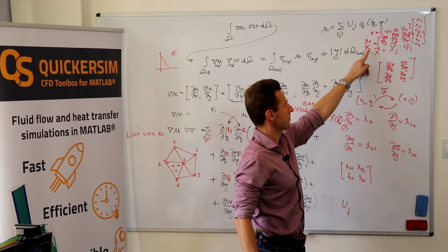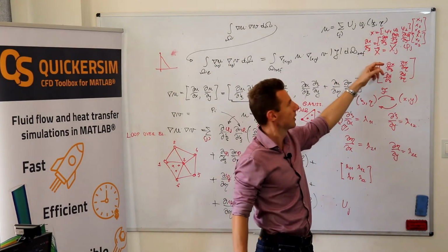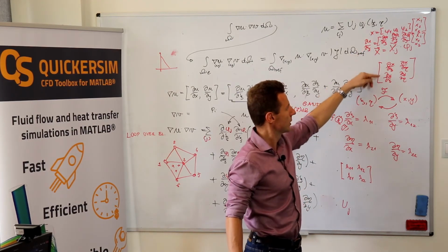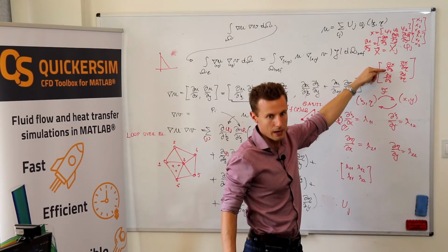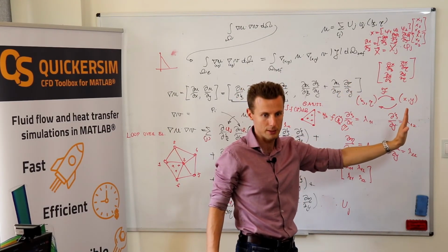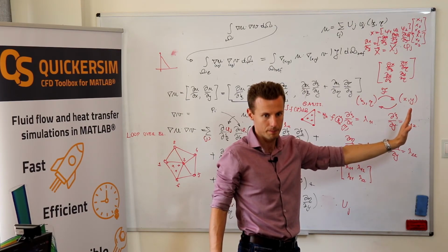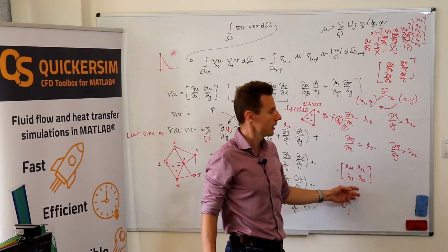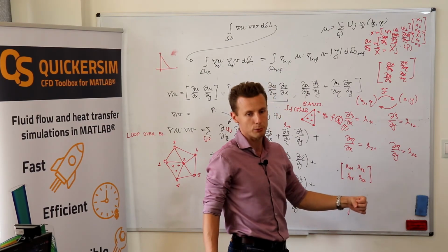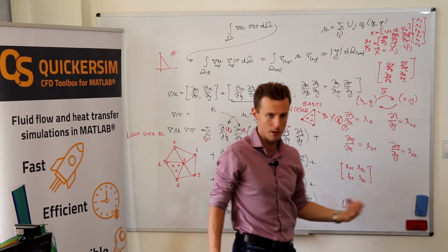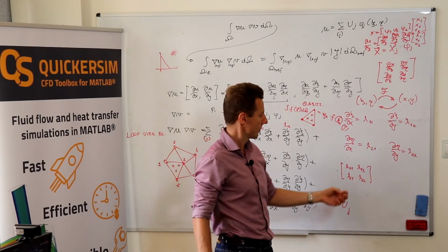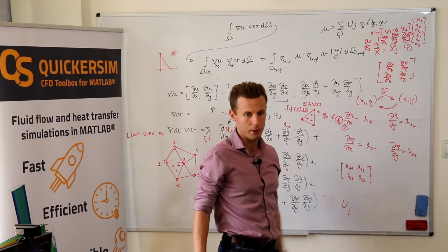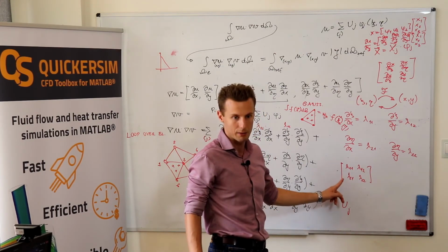With respect to eta, you do the same way. For y coordinate, it would be the same. So you have no problem calculating this matrix, and it's your original transformation from the reference element to the physical element. Then we know that lambdas represent the elements of the Jacobian matrix of the transformation from the physical space to the reference element. So once you've calculated that, you only calculate the matrix inverse to get that.